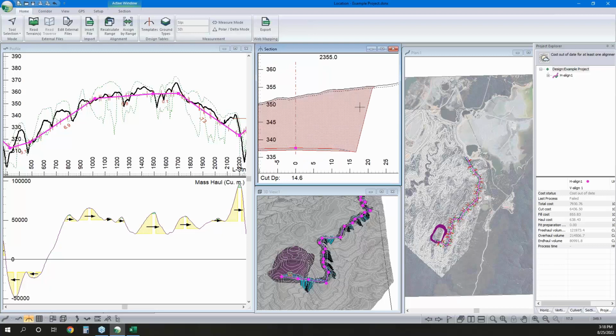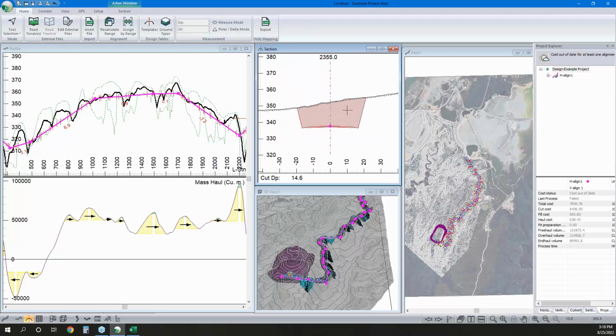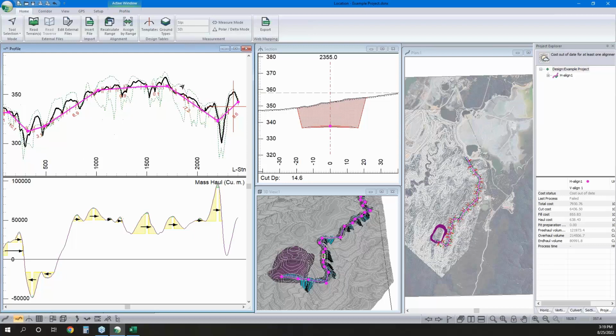Now, before I get into the actual stuff below my organic layer, oftentimes when building a road, you'll want to remove your organic soils. So you don't want that included as your fill, and you don't want to tabulate that as cut and fill for your subgrade because it's not ideal. It'll rot and cause other issues.